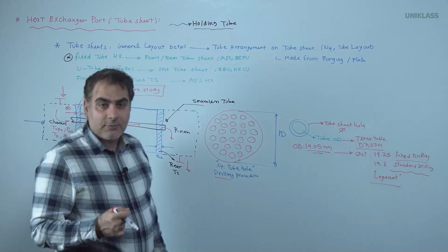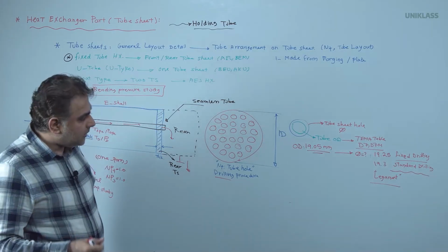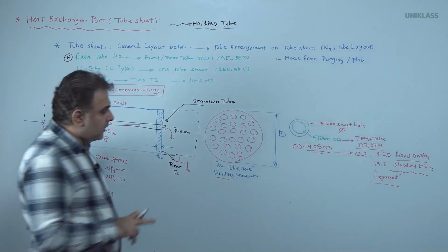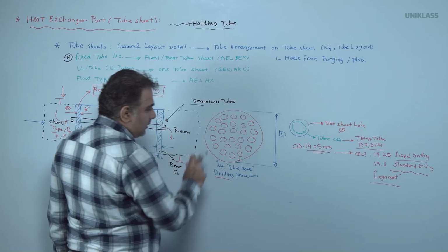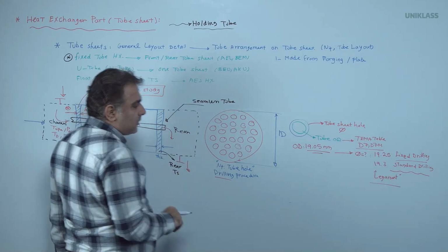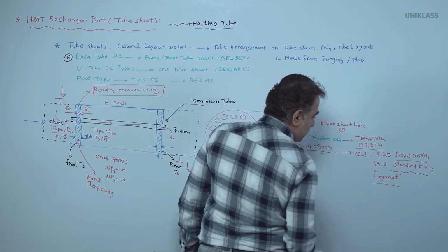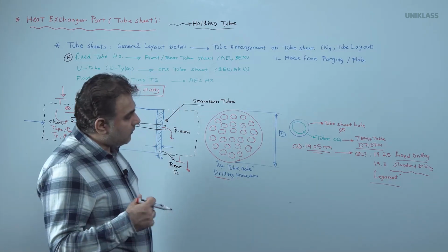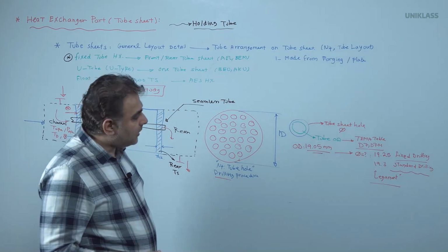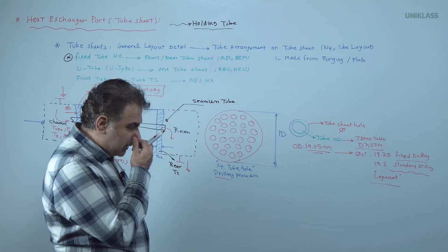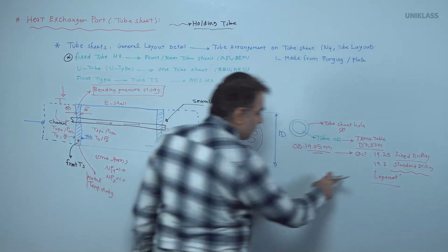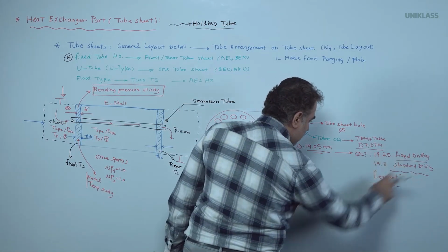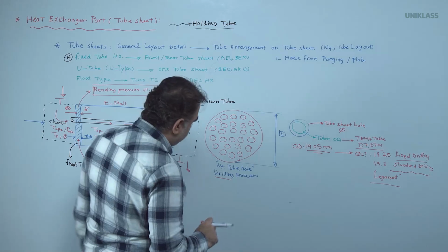Therefore, when we select one tube OD as a thermal designer, the effect on our job is the tube hole data, limitation and standard, based on the fixed drilling and standard drawing. In future, we will see this document, what information the mechanical team has, and what the standard says regarding fixed and standard ligament.